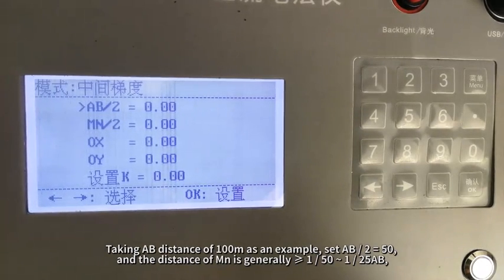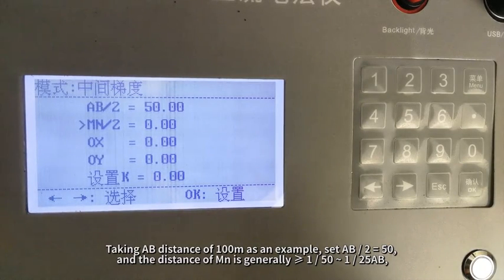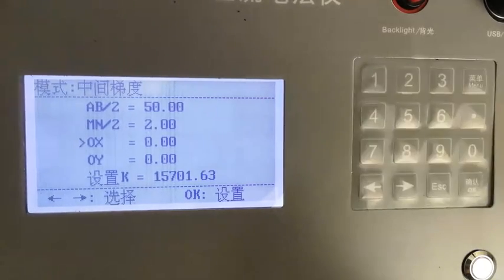Taking AB distance of 100 m as an example, set AB/2 equals 50. The distance of MN is generally 1/50 to 1/25 of AB. Take MN as 1/25 of AB and calculate MN/2 equals 2.